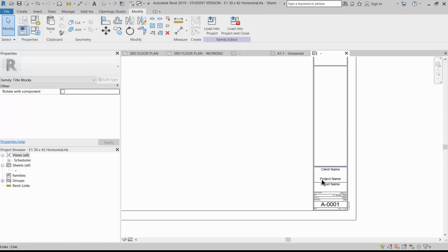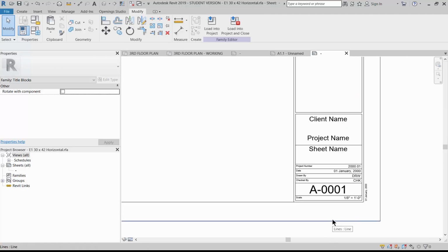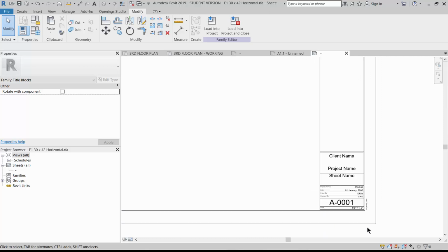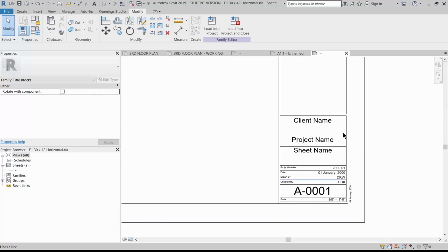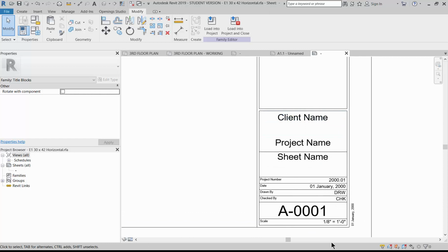You can change the proportion of anything on the sheet. One thing I would suggest not to change is the margin, which is pretty standard, and the width of the title block, which is also very standard, and will leave you with the correct sheet size and proportion that will fit most of the industry standards toward your drawing area. Now, you could make this narrower. I would definitely not make it wider, but the best suggestion is just to leave it the way it is. And look closely at anything else in here that you might need to change.